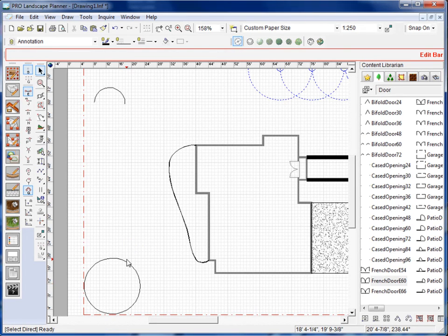Now that's how we use snap tools to create precision drawings. Keep in mind that if you're not used to using snap tools, sometimes they can drive you a little crazy, because if you accidentally turn your snap tools on, your cursor is going to be pushed to other locations. When you have your snap tools on, you'll have a little red indicator that moves around with your cursor.